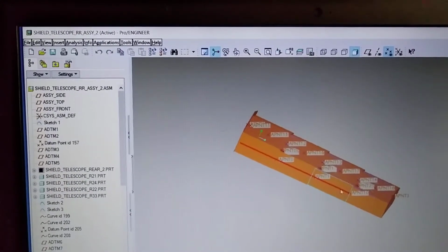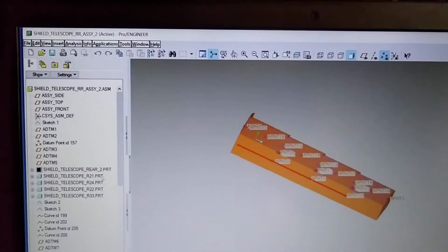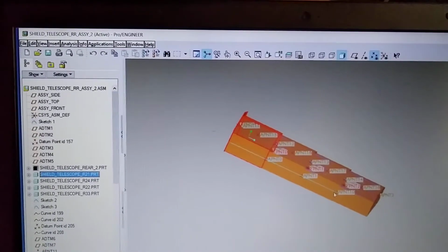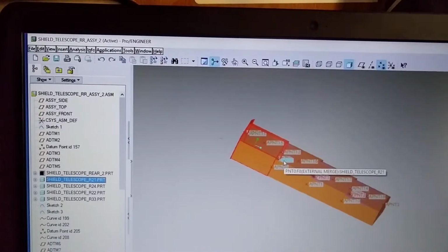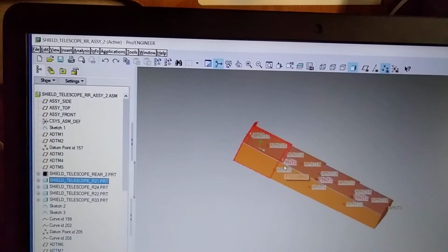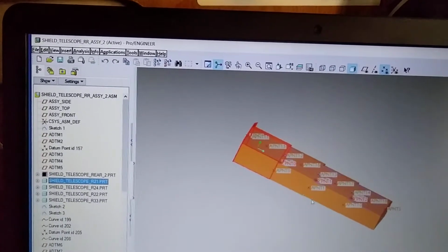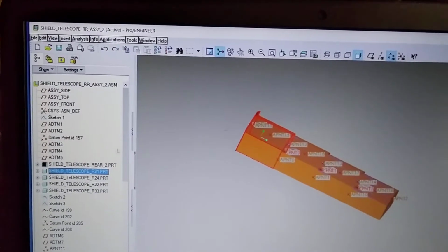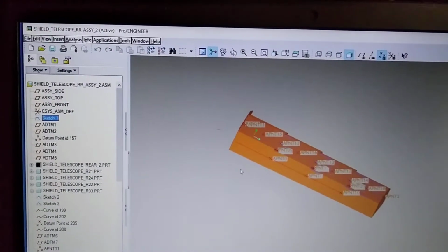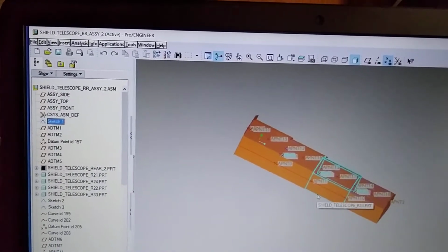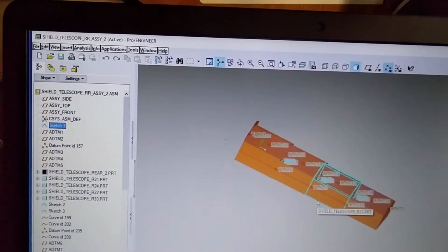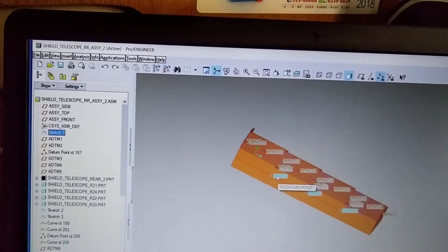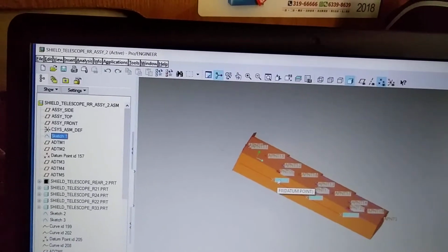So I just need to build 3 sectors here and 3 points, and then assemble each sector related with these points. Of course, I need to build a datum pin to assemble it. Anyway, each sector is assembled into this assembly related with these points, because this curve will change in length during the contraction or extension stages, so they are assembled in a related position.